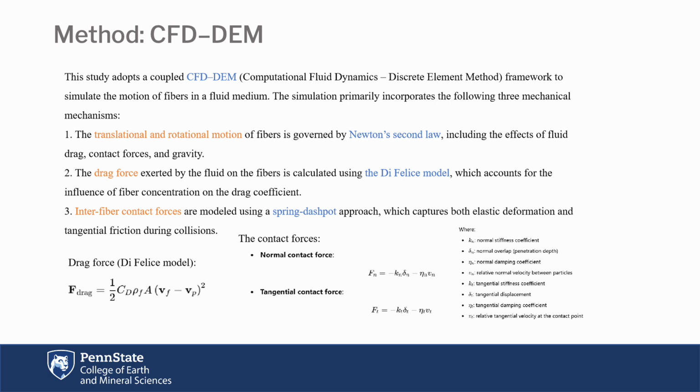The second one is the drag force exerted by the fluid on the fibers, calculated by the DEM model. And the third one is the inter-fiber contact forces, using a spring-dashpot approach. We can also see the mathematical equations as listed.